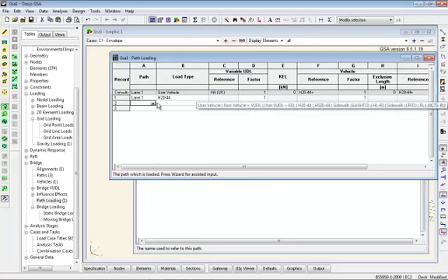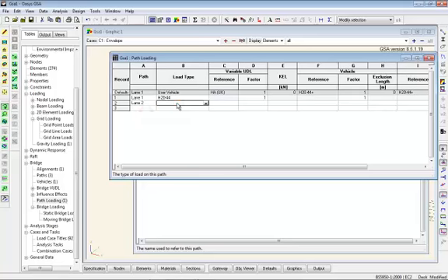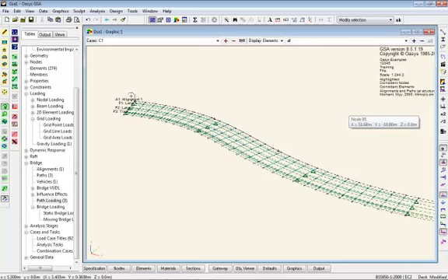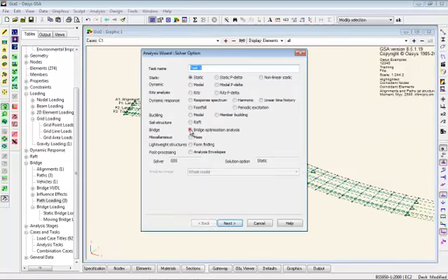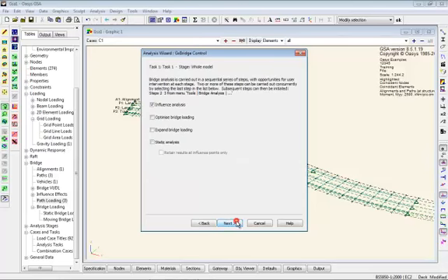Lane 2 is also going to have these vehicular loads, and on the track we then stick a railway load, and hopefully there's a nice little fence to keep the cars and the trains separated. Once we have these in position, you then need to do an influence line analysis. This is a new analysis task. It's bridge load optimization and influence analysis,